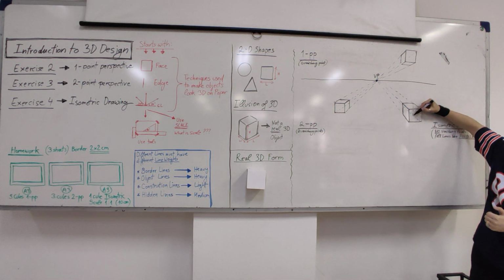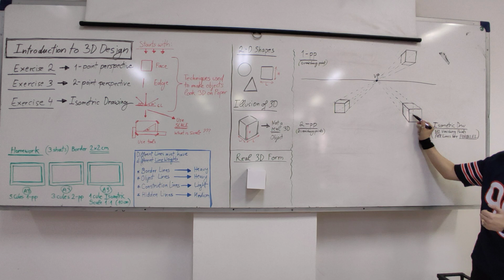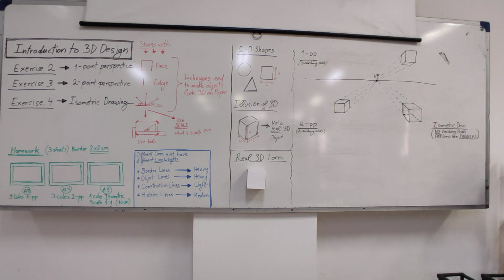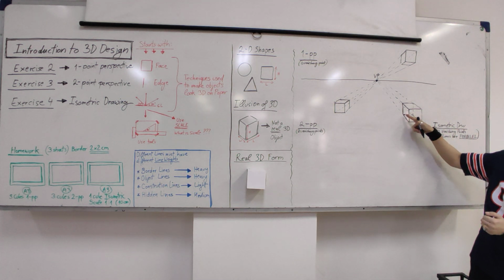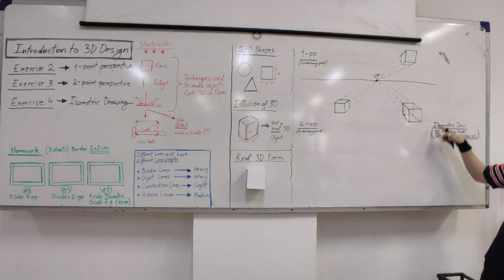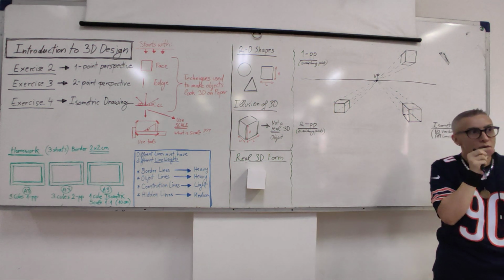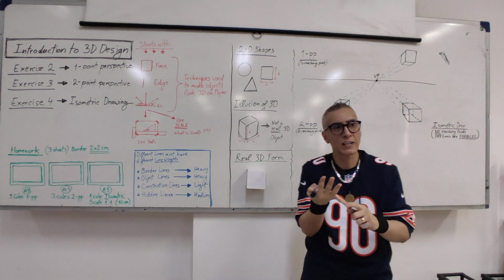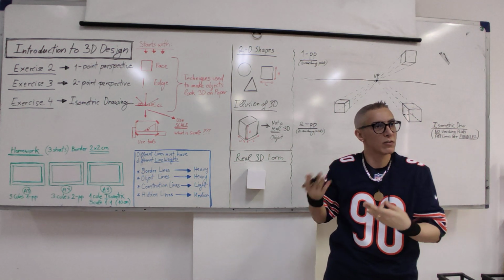So this is a dashed line, and this line we already made it. I will just make it a little stronger. And this point with this point also needs to be connected, okay? Now the cube looks like a glass cube. We can see the internal hidden lines and the external visible lines, object lines. Now, these words that I'm using, object lines, hidden lines, this kind of stuff will keep repeating in design, okay?